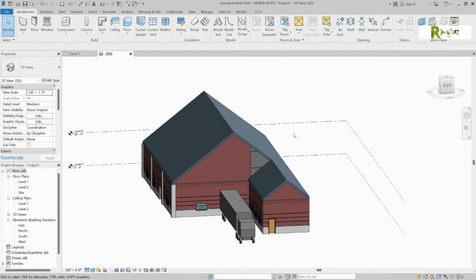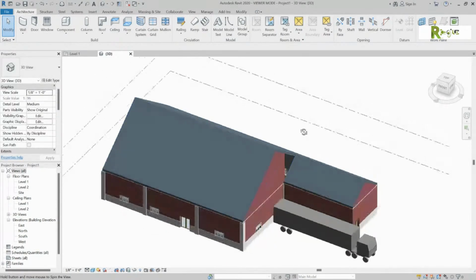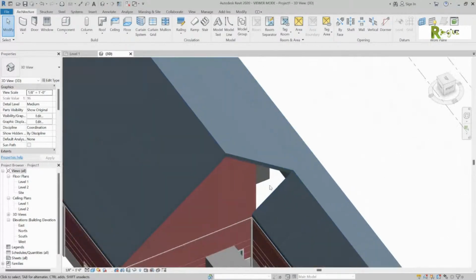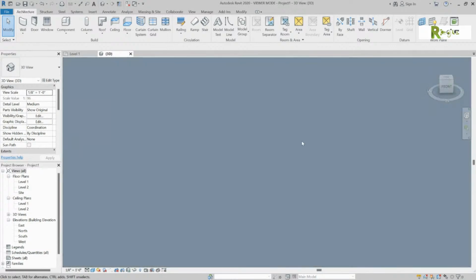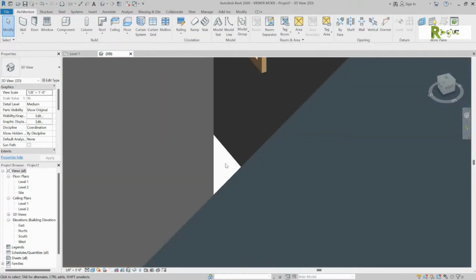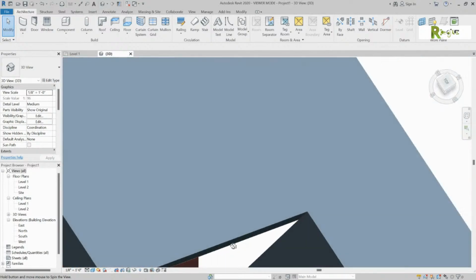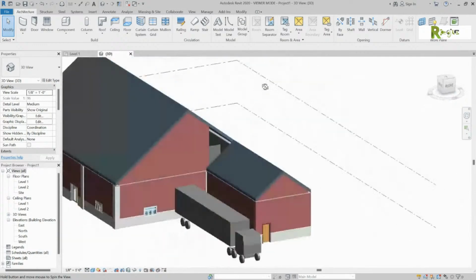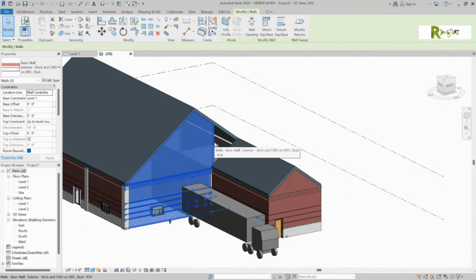And guess what? Is it because there is a parapet on top of the wall? Is that why we're getting that line in there? Yeah, that's why that line is there. That's a wall sweep. And you would have to build another wall above your garage to close that section. Well, let's actually go into that. So this is where typically we would be keeping everything super simple, but for some of the advanced people we'll throw in a piece. Tyler, pick that wall. Eric's got a problem with that white line that's going across it. So I want to show him where that is.